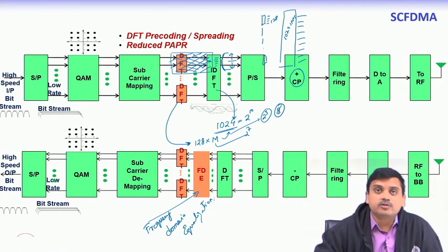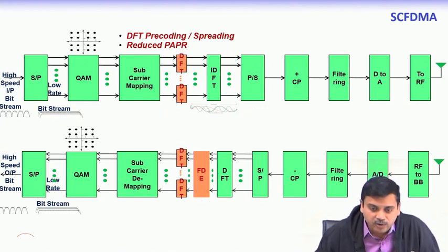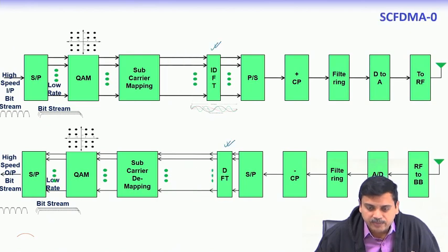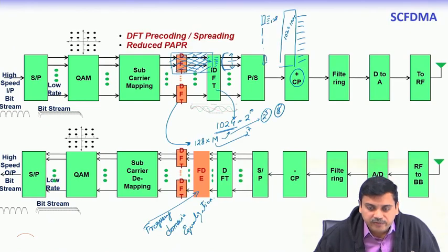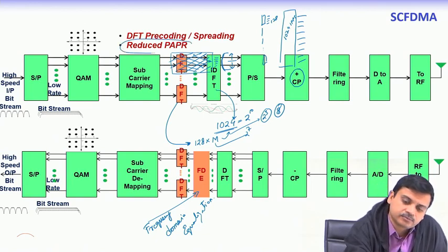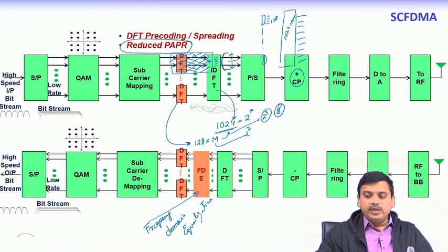Okay. So, this frequency domain equalization makes things very easy. One can use a very simple architecture, per subcarrier only one tap equalization, and hence one can proceed with the things. So, if we follow through some of the steps that we have shown, from the OFDM system to translate to a DFT spread system which has a very low PAPR, because it kind of randomizes parts of the signal, we can actually have the same system with a minor path switching.